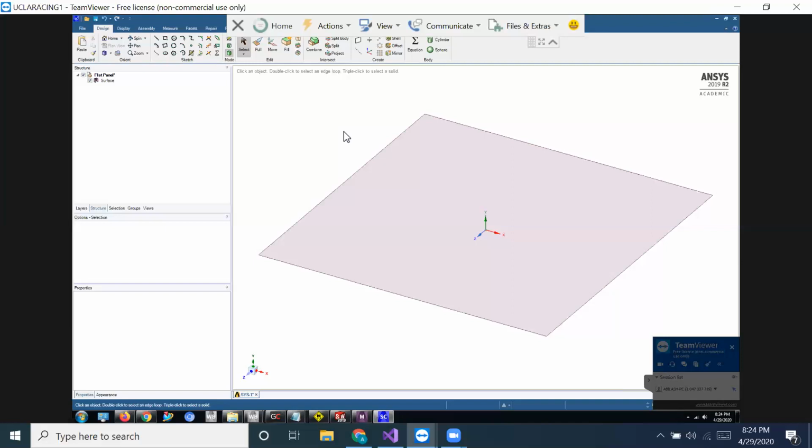So you want to analyze that more in detail. But for the rest of the flat panel, it's not really that important. All they do is pretty much propagate the stresses across from one end to the other end. And you can usually get away with making the meshes slightly larger, so that there's less resources used.